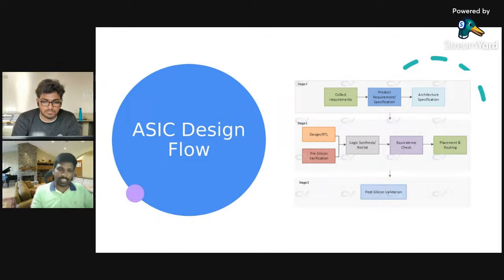So typically an architect will define the architecture and the specification of a particular product, and this product will then kick off into the design phase. This will be started by the design as well as the pre-silicon verification, which go hand in hand, once the design and the functional part of the design is ready without any bugs, by completely validating all the functional cases. In some projects it will sometimes be in parallel, doing the logic synthesis and the netlist generation, and there will be an equivalence check, and in the back end there will be placement and routing in order to get the efficiency out of it.